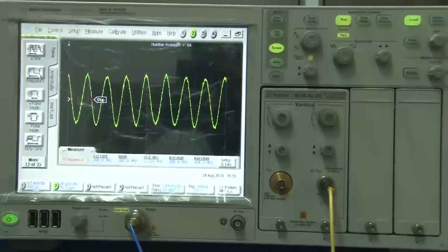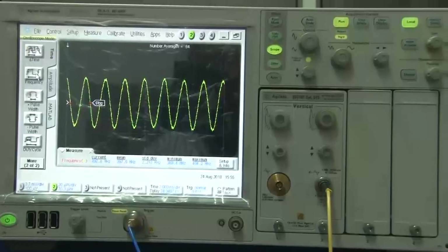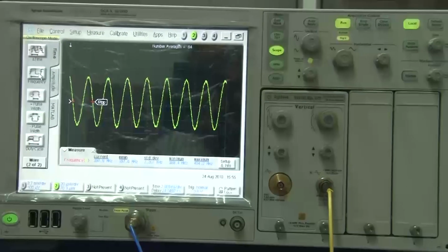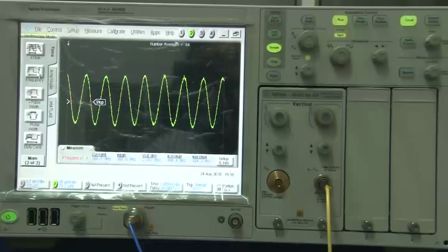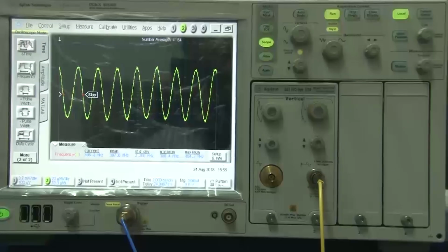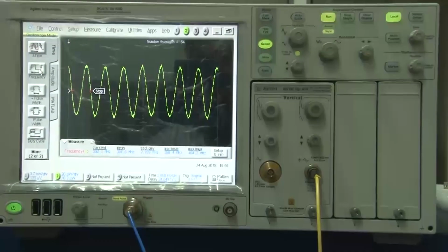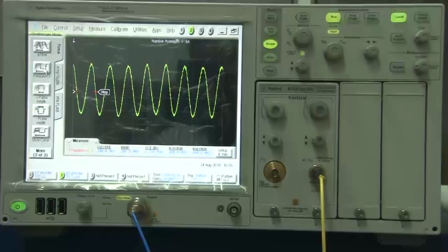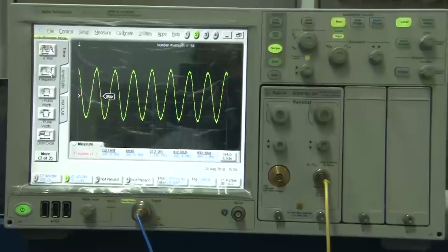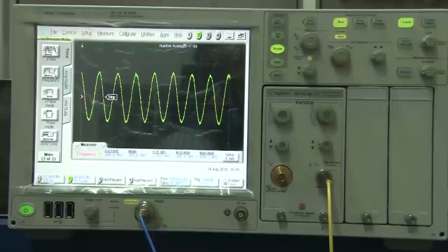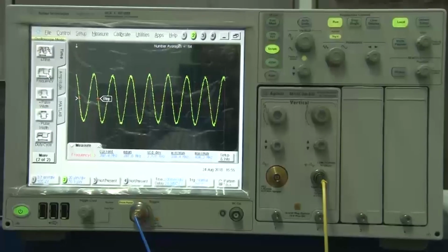so we can align the incoming light polarization according to the axis of the Mach-Zehnder modulator itself, which is a lithium niobate crystal based Mach-Zehnder modulator, and this modulation is on the basis of the electro-optic effect. There are other types of modulators as well, but lithium niobate gives you very high frequency performance and a good dynamic range as well.